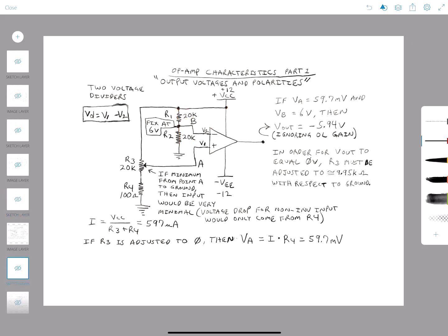All right, that was pretty straightforward, easy. And so now, let's take a look at this leg right here. This is the most important leg. What we need to do first here is calculate our total current running through this leg. Forgetting that we have a pot right here for a second, we know that that is also a voltage divider network as seen earlier. But now we need to determine total current. So in this case, we have current flow this way, all the way back up to our 12 volts.